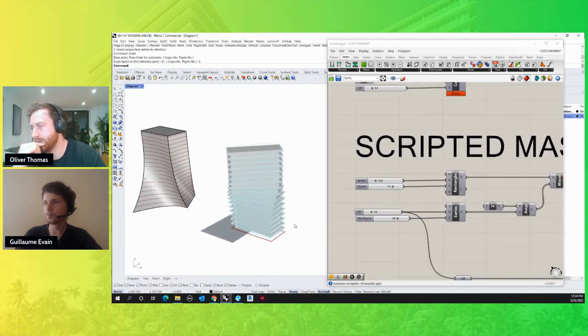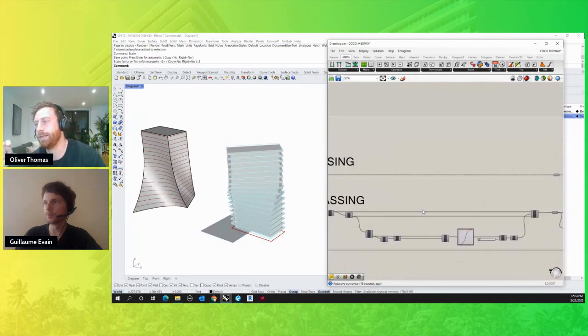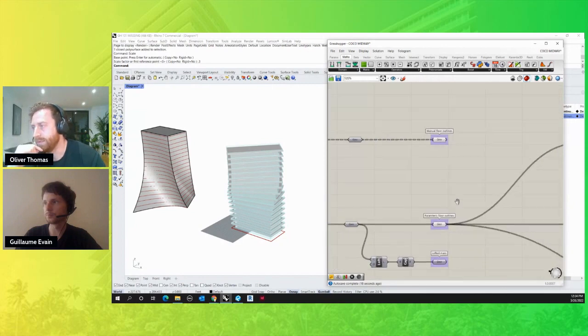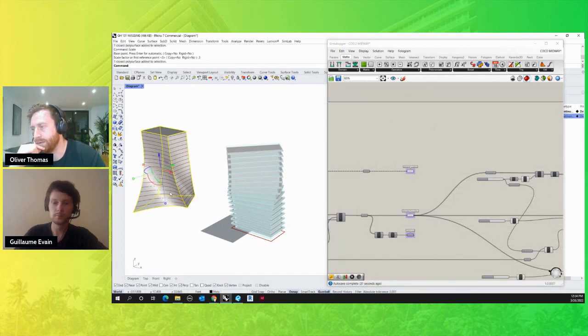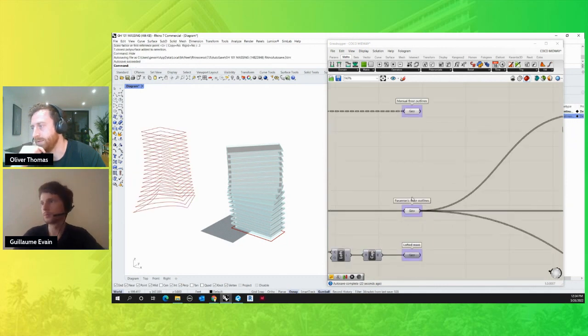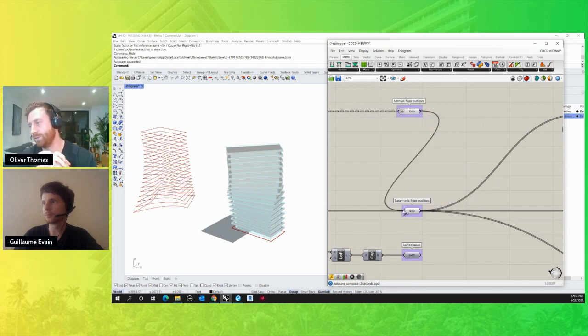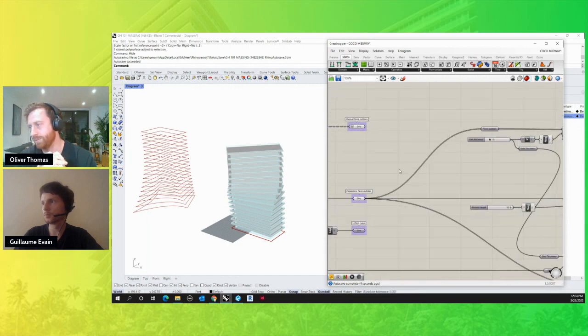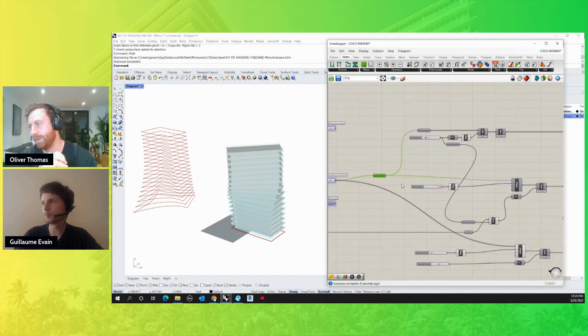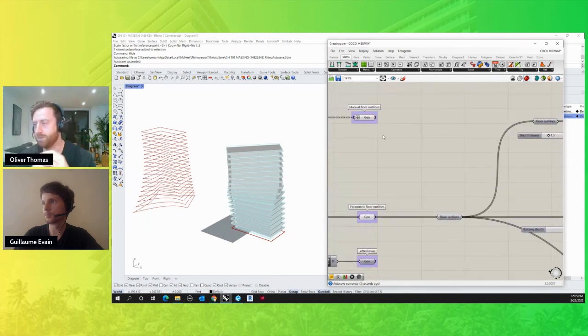So I think what's also cool is now we kind of forgot about the manual mass, so we can go back and hide the manual mass in Rhino, and we'll have to do a cheeky bit of flattening to bypass any problems, which we'll discuss tomorrow. I think this is the cool part: once we've created the script, we've got our parametric massing, but then we can apply this exact same thing to our manual massing really quickly. And it just illustrates the pros and cons of each one.